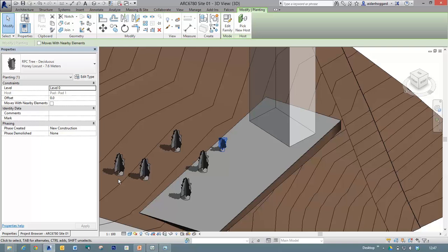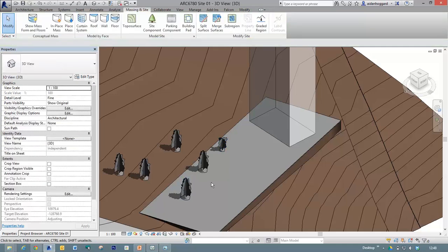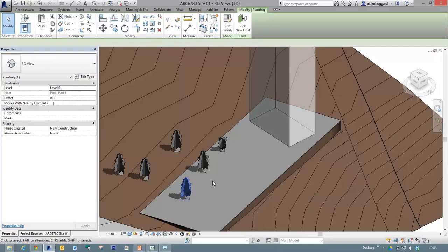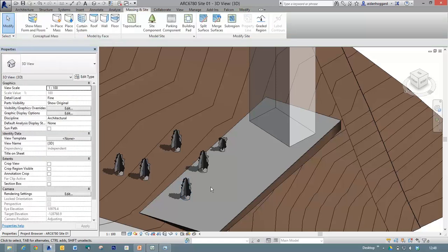But what you need to be slightly wary of is if you start importing hugely complex trees into Revit, your simulation will have problems. Simulation for energy and for daylight will not cope if you have hugely complex files. That's why you bring in these trees rather than a better tree which has 4,000 individual faces on it. So that was trees very, very quickly.